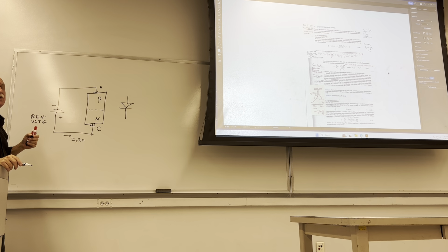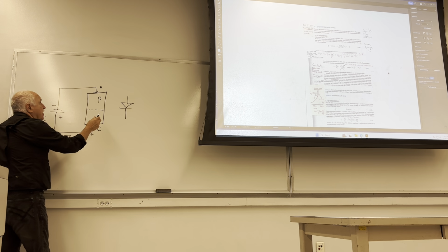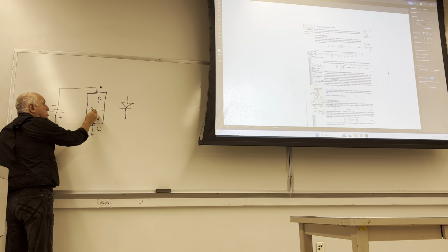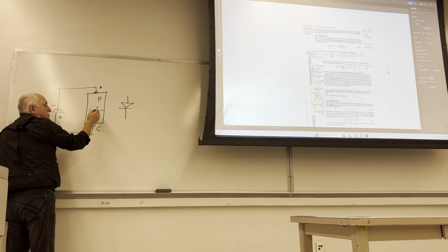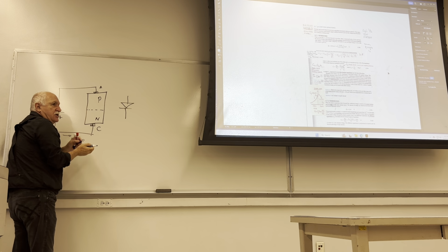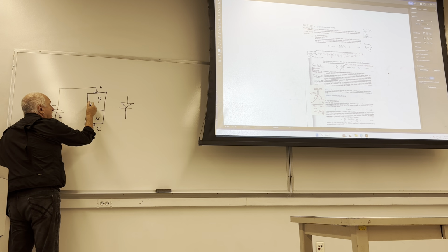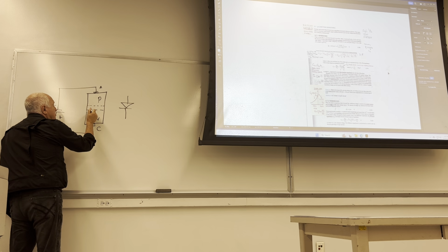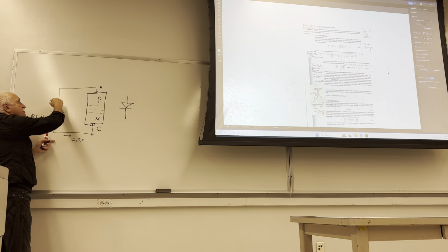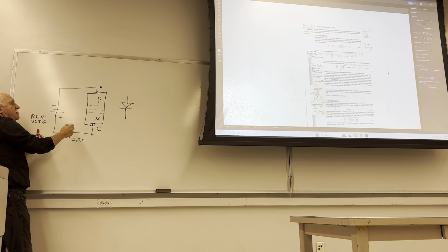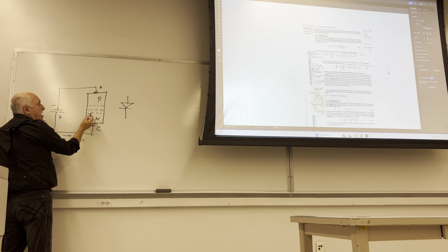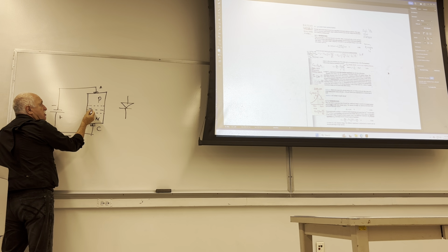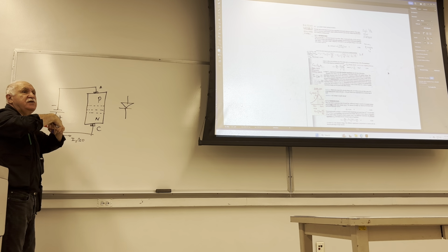However, what is in the diode is the P and N regions, which consist of holes and electrons, an abundance of electrons here. When they are interfaced, even with a 0 voltage at the terminal, part of the electrons migrate from the N-type region and go towards the P region, and they fill the holes.